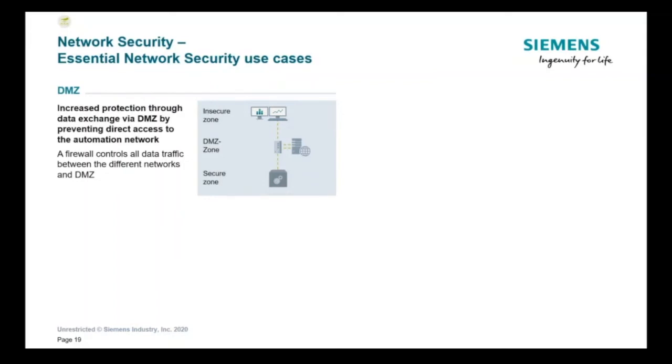So in most cases, what gets placed in any DMZ zone is any SCADA system, any server, or anything that does not need to be accessed from inside the plant to run, but can report its data up into those servers, the asset management systems, or anything else of that nature. And then the insecure zone above that is typically where you will see the uplink into IT, so that way the managers, the C-level people, can actually see the data reporting, but they don't have access down to the plant floor. They don't need access to the plant floor, they only have access into the DMZ zone.